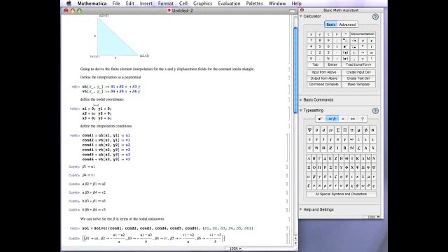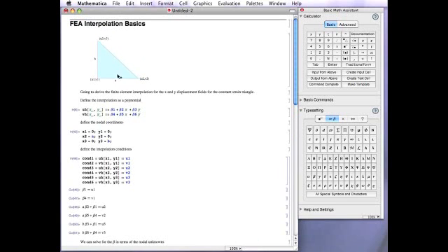Now, we could change it, though. Let's use the triangle that's sort of its upper neighbor, where this would be node 1, node 2, and node 3. So node 1 has the coordinates (a,0). Node 2 has the coordinates (a,b). And then node 3 would have the coordinates (0,b). Now we can go through.